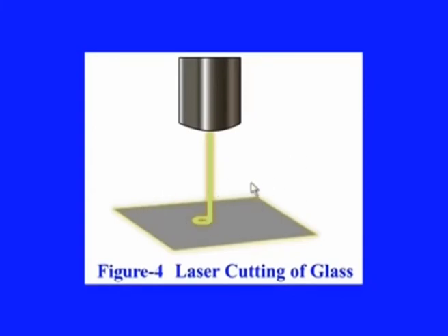This is a glass material and this is the laser head, and this can cut a hole or even a contour of required geometry. Then in cutting and grooving, laser can be employed very efficiently. Powers in the range of 200 watt to 1 kilowatt are recommended for cutting of steels. Oxygen jet assistance is found to be suitable for most metals, as the gas liberates additional energy by the exothermic chemical reactions that occur in the machining region.